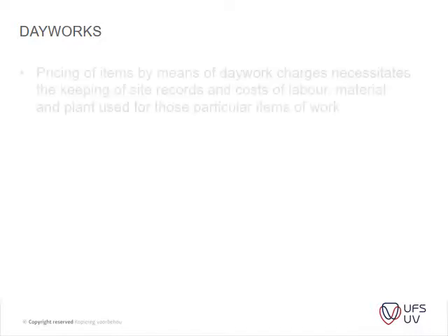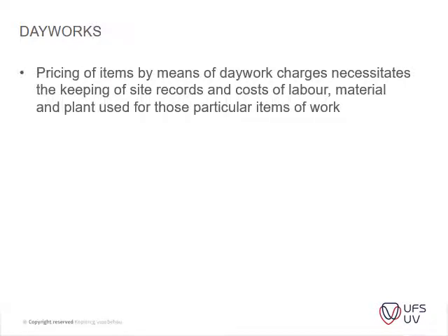Okay, day works. Day works is basically pricing of items by means of day work charges. It necessitates the keeping of site records and cost of labor, material and plant used for those particular items. So day works is basically labor rates that you've got in your bill of quantities. The civil engineers like to use that, and that is usually where you have a tariff for instance, a bricklayer, or a tariff for a certain type of artisan, or just a general labor on site.